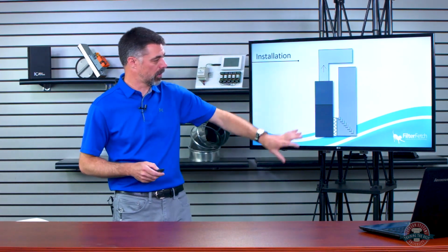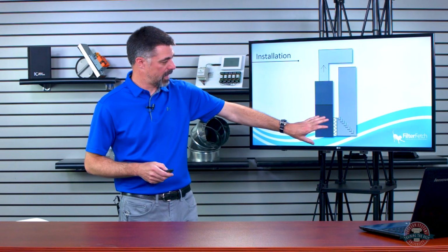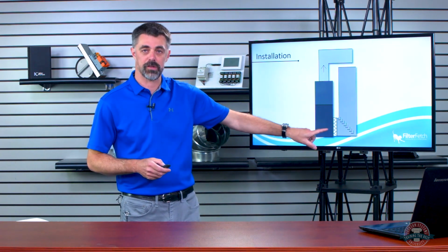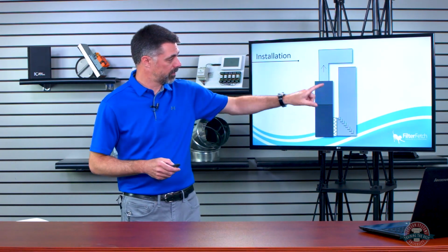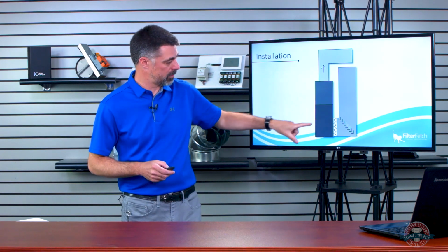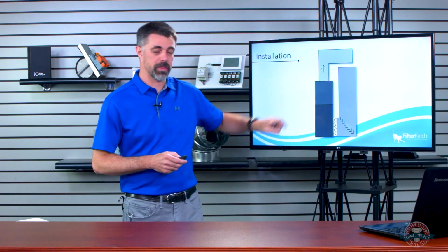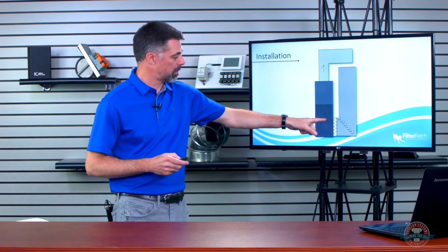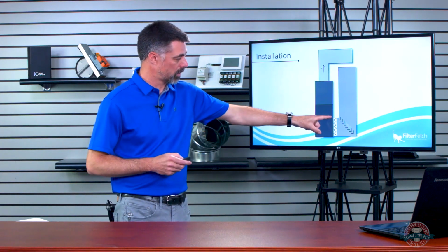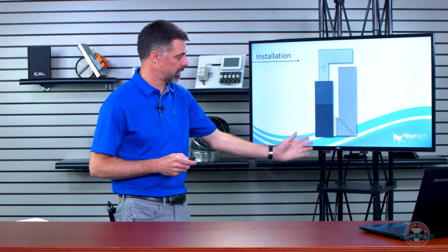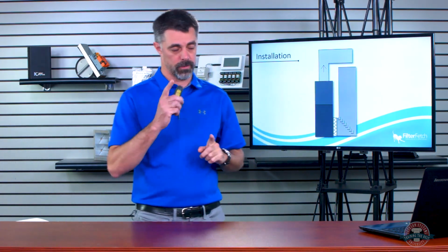So this is one option. And again, this is typically a gas furnace; you'll see it set up like this. If this is, say, an air handler, you'd need to have a box under here with that going in. And we'll take a look at a couple things on that later on with some other configurations. Because a lot of times if you've got a box right here with an air handler on it, you want another set of turning vanes going across here to aim it up into that coil properly so that we get straight airflow going into the coil. And you'll see a neat picture on that later on as well.